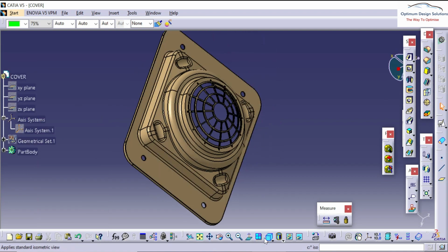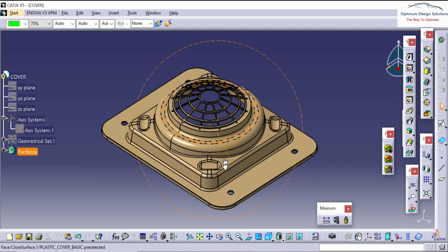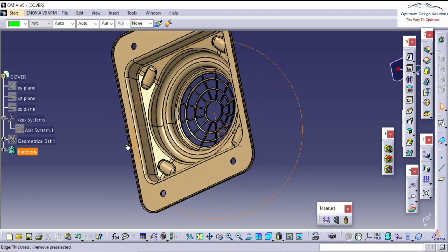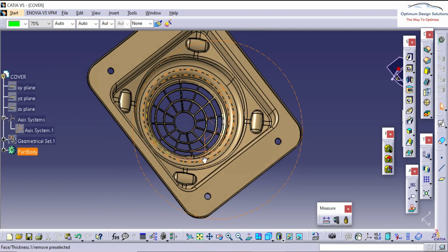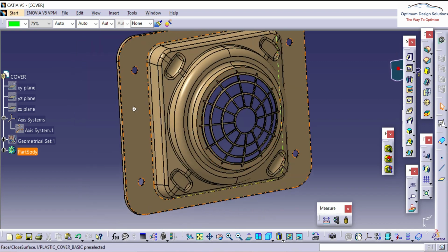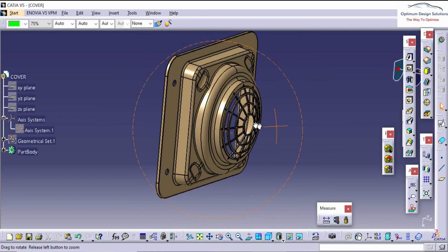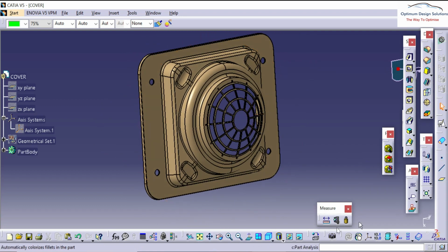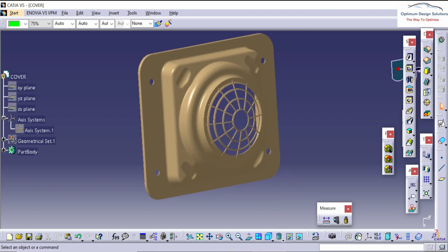So for that, activate the material mode. We need to check whether this component gets cleared from the tooling or not. So here we'll activate the material mode, and where is the draft command?